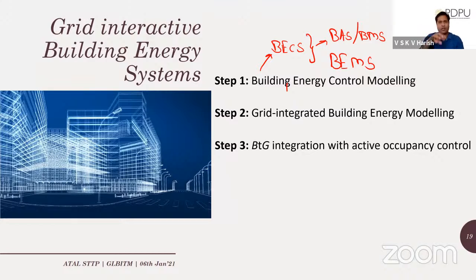And if that same particular room at the same location is being used as a gym, then my metabolism would differ, and the thermostat set point setting for the air conditioner would differ. Right? So that is the aspect that was taken into consideration. So hence it is necessary and important that even when you talk about this energy efficient building design, or during the operation, the retrofit analysis, the occupancy comfort needs to be taken into consideration inside your models as well.